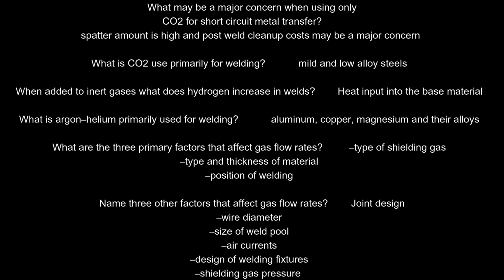What may be a major concern when using only CO2 for short-circuit metal transfer? Spatter amount is high, and post-weld cleanup costs may be a major concern. What is CO2 used primarily for welding? Mild and low alloy steels.